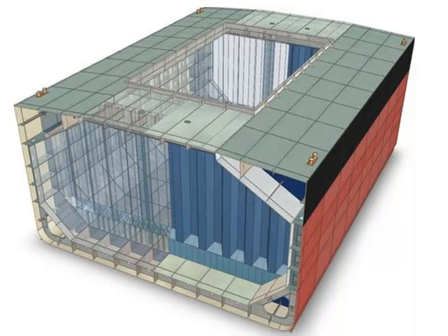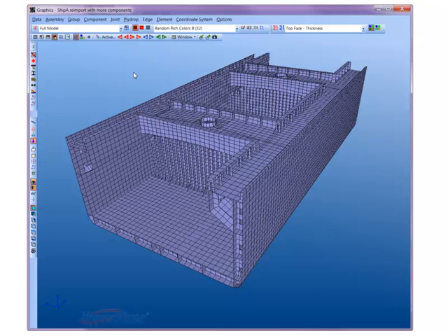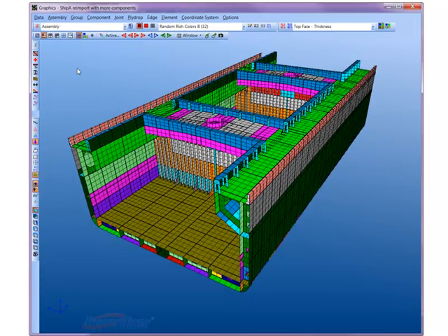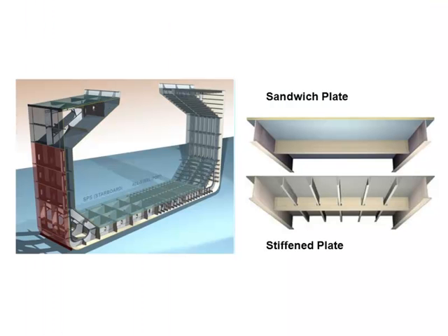Our goal also includes updating the CAD drawings with sizing data and the finite element model used for analysis. In Hypersizer, updated FEM properties for structural members are displayed with color. A section of the ship hull shows uniformly spaced internal substructure of transverse frames and longitudinal stiffened panels.